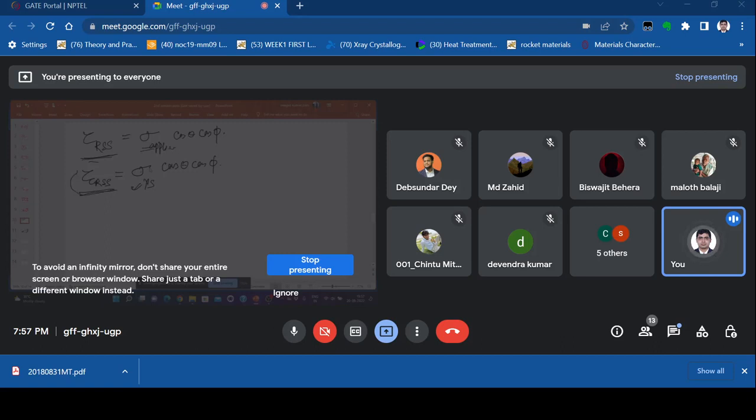So this is a constant value. So this depends on the orientation. So when we are changing orientation, this tau CRSS doesn't change, it remains constant. This yield stress, this is our yield stress, so this changes if we change orientation of loading.